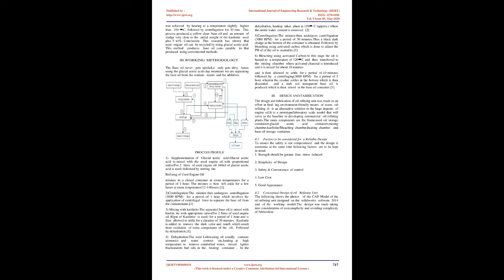Sedimentation/decantation: at the end of the acid treatment step, the acidic oil was allowed to settle for 4 hours to form sediment at the bottom of the beaker. After this period, the acidic oil was properly sedimented and was decanted into another 500 ml beaker, while the residue, i.e. acidic sludge, at the bottom of the beaker was discarded.